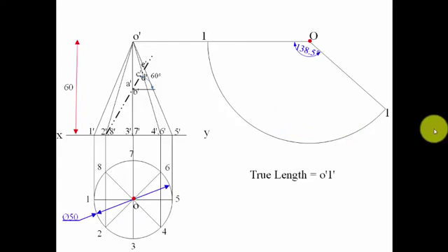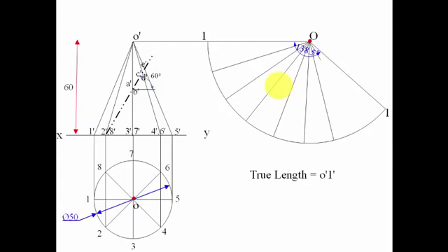Let's have this point as 1, and now we need to divide this particular section into 8 equal parts. It should look something like this, 8 equal parts. So initially you saw this overall angle over here, 138.5. You can bisect this angle. Angular bisection is pretty simple. When you bisect this angle, it gets divided into 2 equal parts. Then pick up any one portion, then divide it further into 2 parts. So 1 can be divided into 2, 2 can be divided into 4, and 4 can be made 8. That's how you need to go about your task.